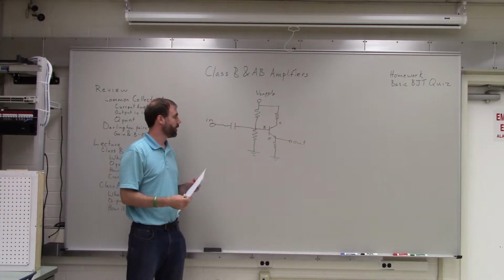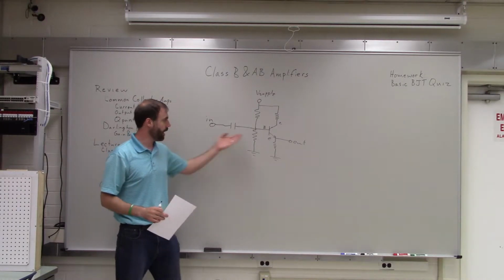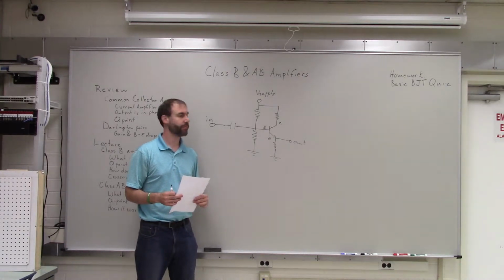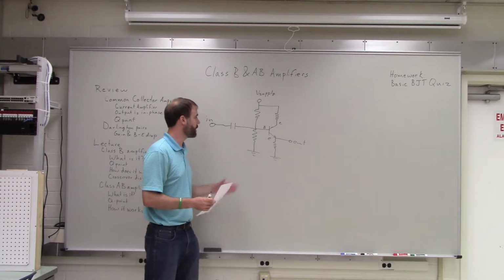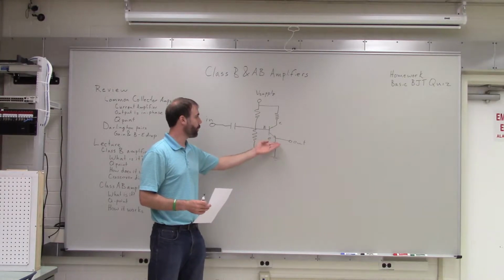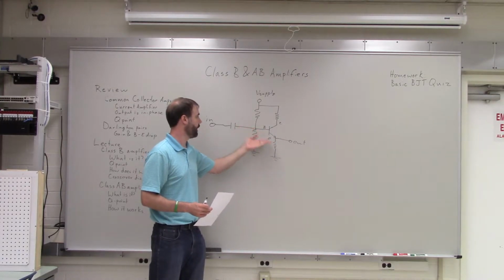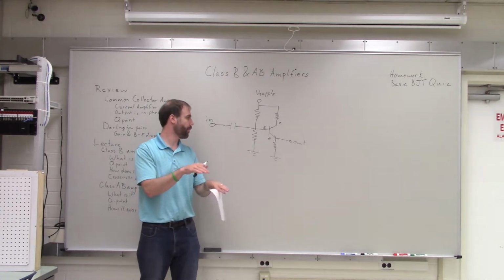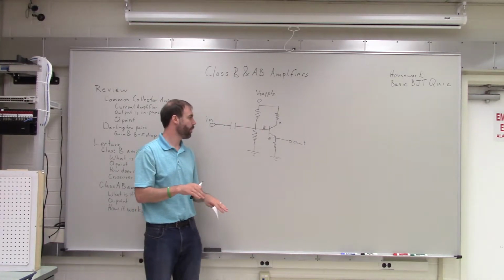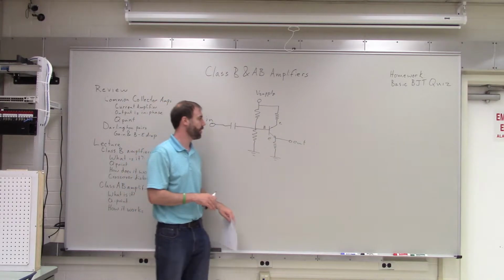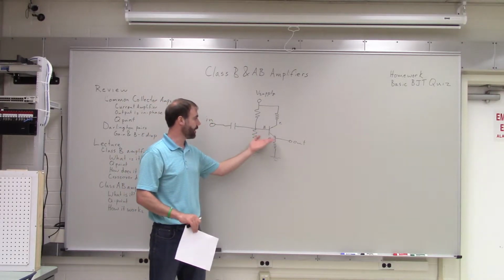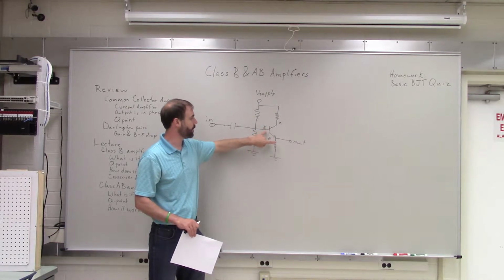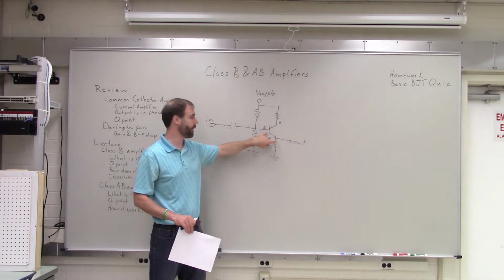And another name for this was the voltage follower amplifier, right? Because the output voltage followed the input. So as the input voltage goes up, the output goes up, and when the input goes down, the output goes down. Another way to see that is that the output, remember that the transistor acts almost like a pair of diodes.